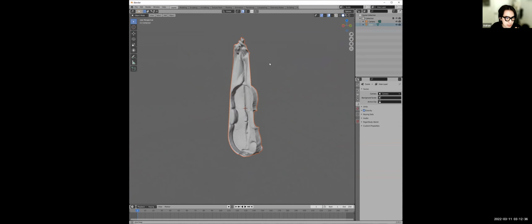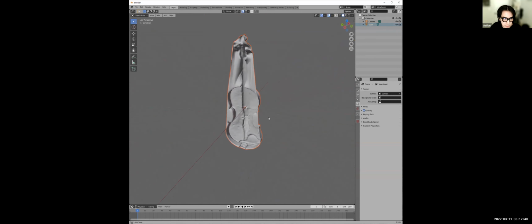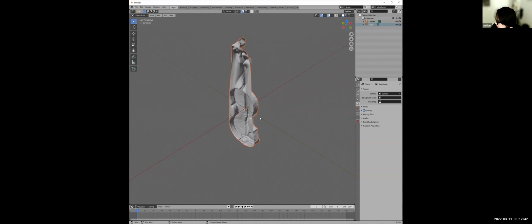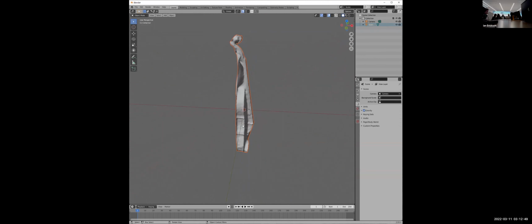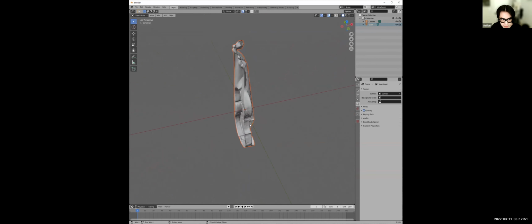One thing you'll notice is that it's gray. There's no material. You can't see a material, and the back is open. I think, Ian, you mentioned that with RealityCapture, it exports as a closed mesh. Yep. Right. Okay, good. So that's fine. Then we won't have to do the thing that I'm about to do, but I'll show you in any case, in case you use some other method of getting a photogrammetry, or you find something online, for example, some point in the future, you'll need to close the mesh so that it can inflate. Otherwise, of course, it won't inflate.